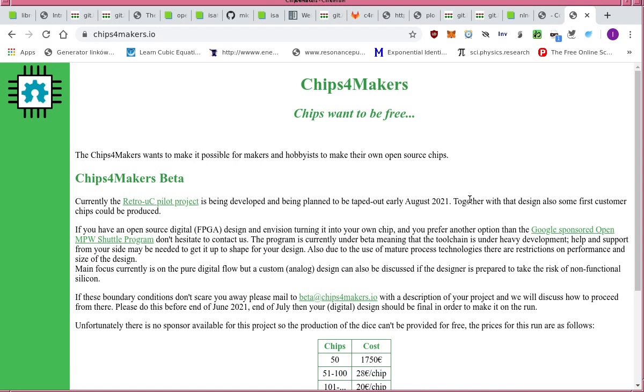One of them is FreePDK45, which is an academic PDK for training students. And recently Skywater have released their 130 nanometer PDK. Normally, you would do this under NDA. Staf himself has to run it. He has access to, for example, the TSMC 180 nanometer PDK. So under that NDA, he runs the program, which generates the cell library suitable for TSMC 180 nanometer.